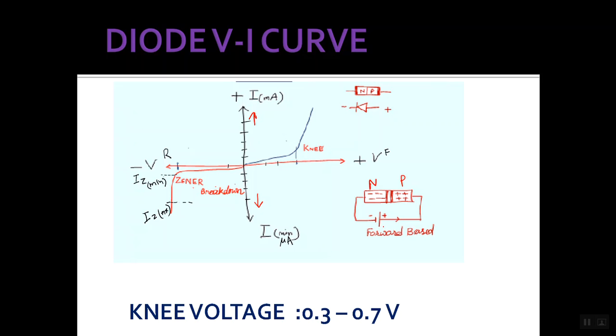हम जब इसका वोल्टेज बढ़ाएं, suppose you have applied 0.1 volt battery. So what will happen? There will be very less flow of current in the circuit. See, you are increasing this forward voltage. There is very less current flowing in this. Again, you are increasing a little more. There will be again a slight increment in the current, and for some particular voltages.